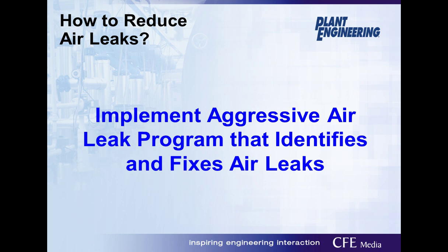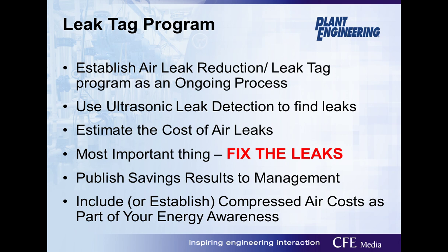You need to really implement an aggressive air leak program that finds and fixes the leaks. Leak tag programs, you should establish on an ongoing basis. Again, we talked about ultrasonic leak detectors. You want to put the cost in and estimate those air leaks. The most important thing is fix them.